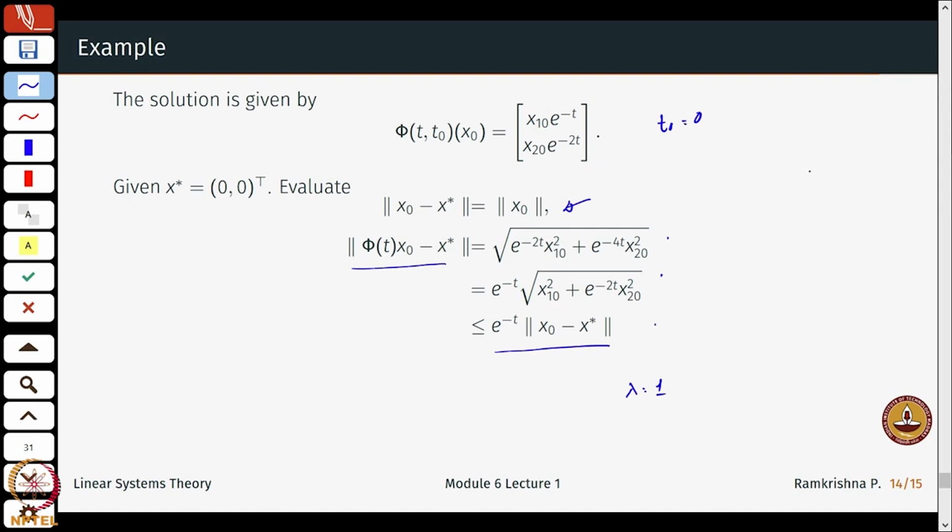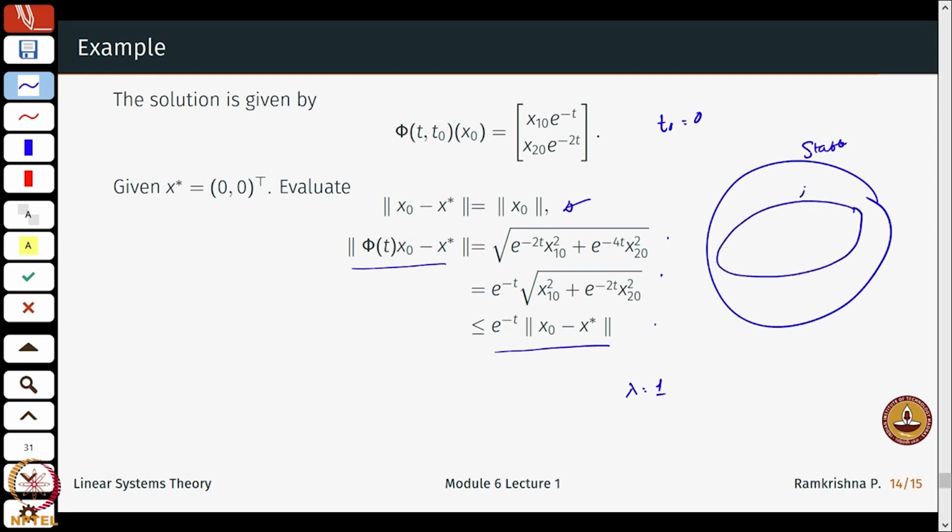Now so far, we know that this is stable. Something inside could be asymptotically stable, which is a smaller subset, and exponential stability is an even harder condition to check. So this is the strongest condition to check. Stable is just a bigger set. Asymptotically stable systems are stable, and exponentially stable systems are asymptotically stable.